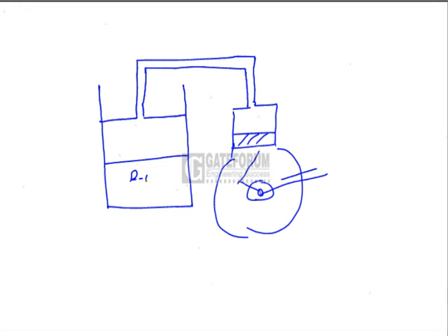This is R12 liquid. Now I am just sucking the refrigerant vapor the moment it is formed over the liquid, and the vapor is being drawn by the piston movement.